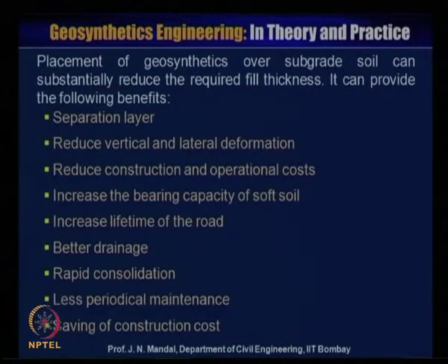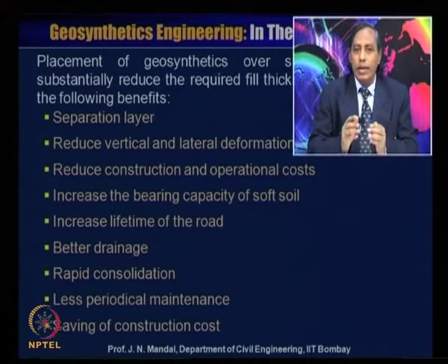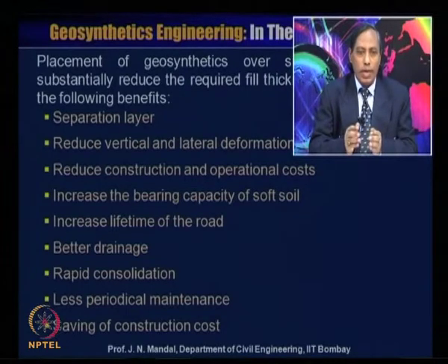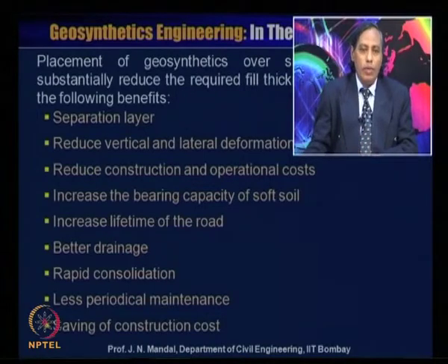So, placement of geosynthetics over subgrade soil can substantially reduce the required fill thickness. It can provide the following benefits. It acts as a separation layer, reduces the vertical and lateral deformation, reduces construction and operational cost, increases the bearing capacity of subsoil, increases lifetime of the road, gives better drainage, rapid consolidation, less periodical maintenance and saving of the construction cost.